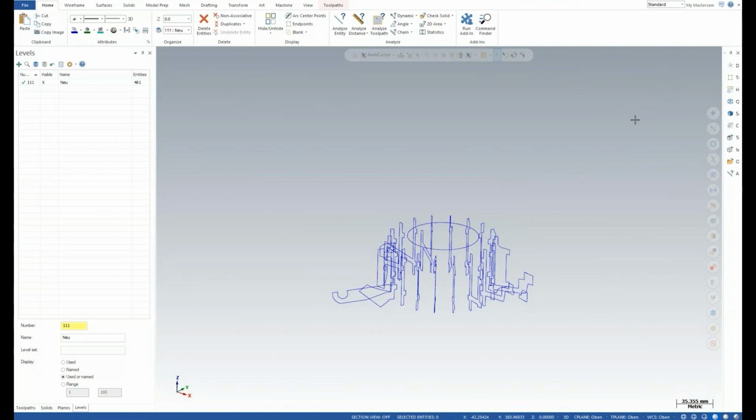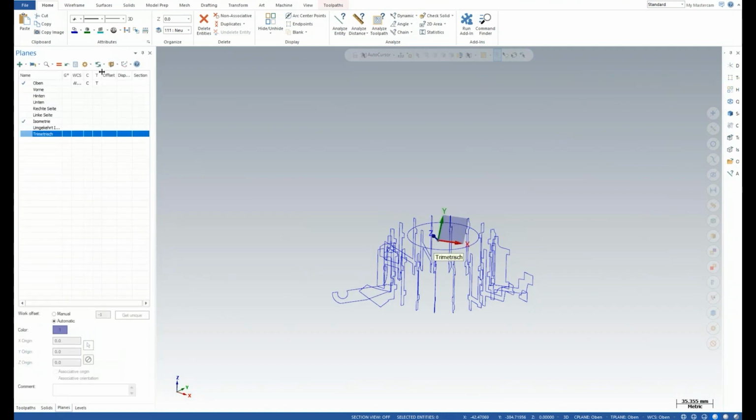There's a couple other questions that just came in. It's a 2020 related one. It says on 2020, change view, C-plane can't follow view plane. That's a setting in the planes manager in the follow options. You have that control here. It was uncoupled and broken out into different things. So that's how it is now controlled, since 2020 when that changed.